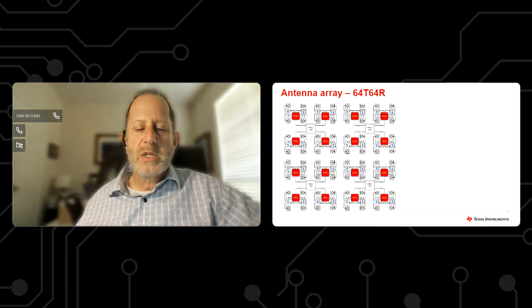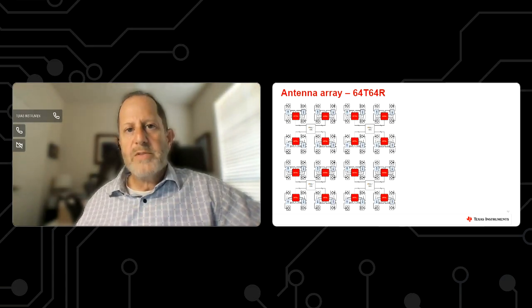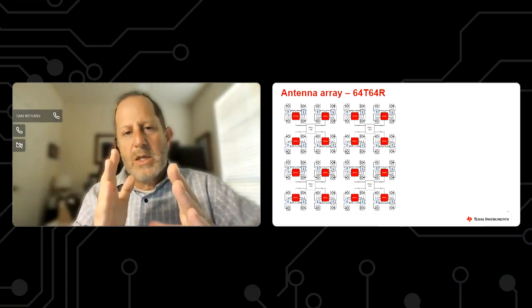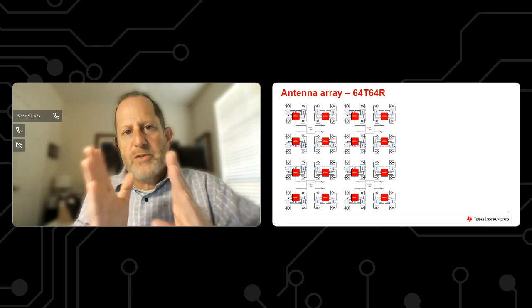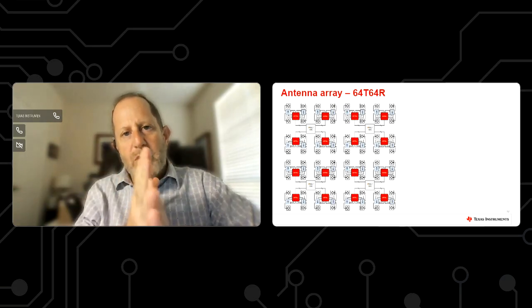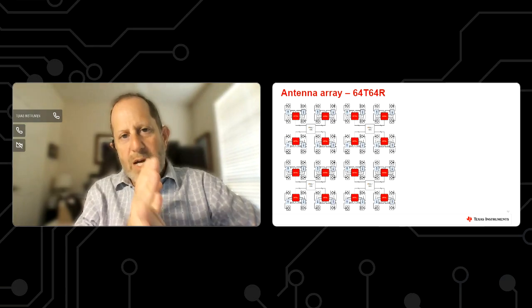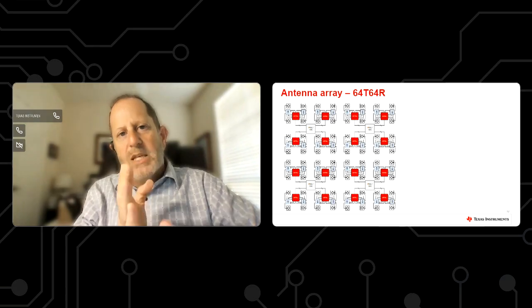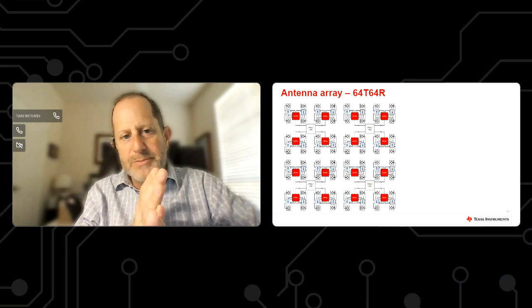We can adjust sysref windowing using some of our newer clocking devices, so that if there's some sort of a delay there and we need to shift or delay to get within the sample and hold window of the high-speed data converters, we have the opportunity to detect that and to adjust that sysref in order to get things properly aligned.